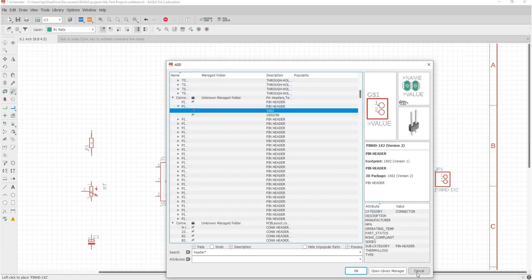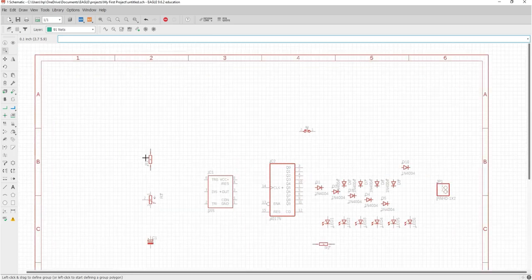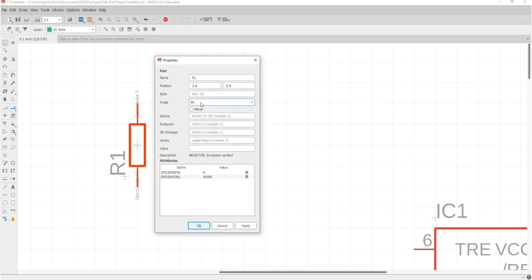After all the components we need are now placed on our schematic working space, we should give value to the components we use. It is used to ease us when we're making the PCB layout design and when assembling the components to the PCB. To change the value, click the targeted component, then click this information symbol on the command toolbar.